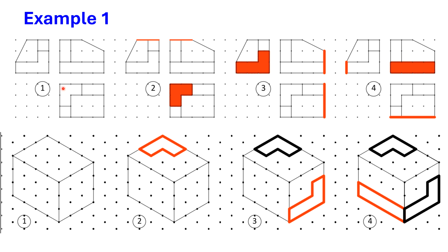Now you know the length and width, so you will be drawing the front view box here, the front view window, and this is the left side view that will be drawn on the right side. The width is 30 mm by 30 mm, so you draw another square. And this is the top view. The top view length is 40 mm and width is 30 mm, so you will be drawing this on the top of this box. Wherever you want to start, you need to start the top view from here, the front view planes here, and the side view planes here. So that is the first step.